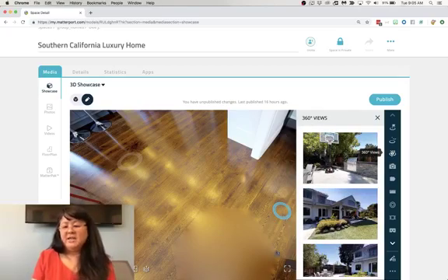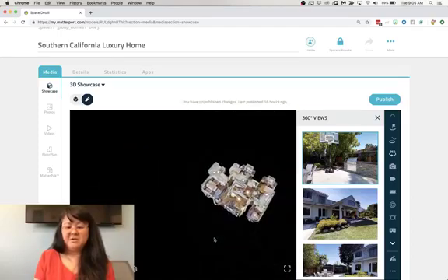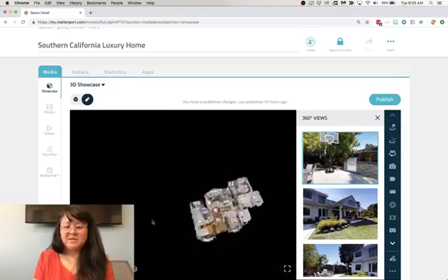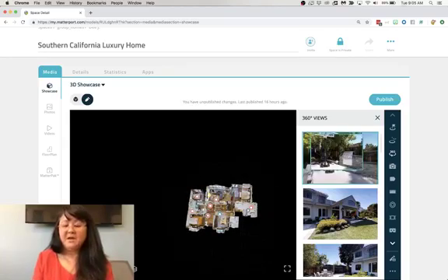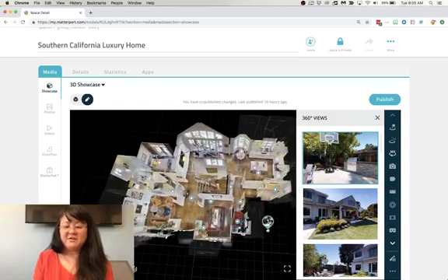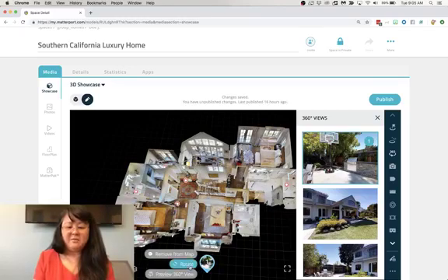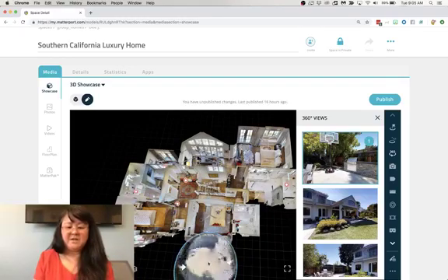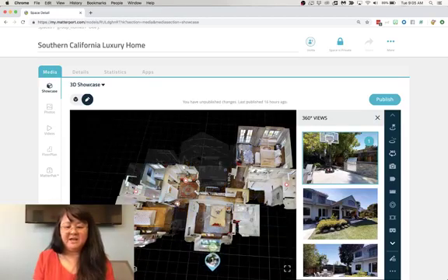All right. The next icon is the 360 view placement icon. This allows you to place your 360 views within Showcase Edit Mode as opposed to having to place them within Capture. So here we have an example. Suppose I'd like to place this first 360 view. I just simply click on it, drag it to the location where I want it to be. So for example, if I want it there, I can then rotate it so that it's facing in the right direction. I can also move it by clicking on it and dragging.